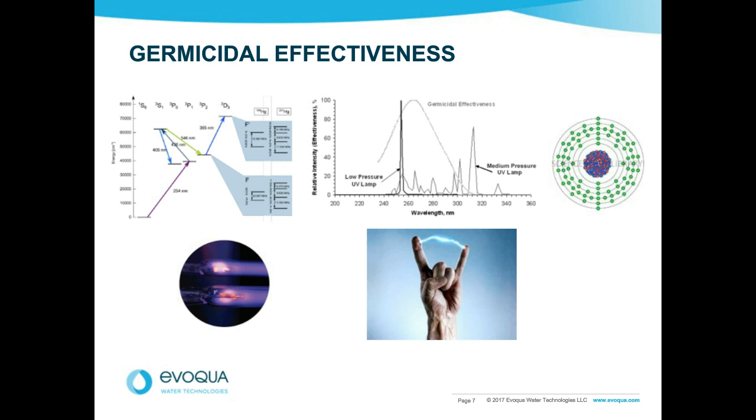We have to be careful where we position the UV. If the water is high quality to start with, we can get hydroxyl radicals coming off the UV system, which can actually damage the membranes. We've got to position the UV far enough away from the membranes to cause no damage. But yes, it can be done. If the questioner wants to approach me or Dave McCarthy offline, we'll give them some cases as to where that's been done, what to look for, and you will see.